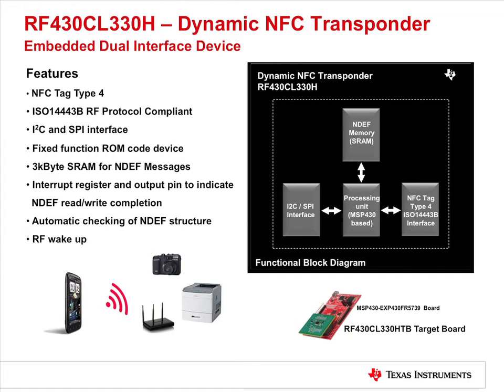This allows NFC connection handover for an alternative carrier like Bluetooth, Bluetooth Low Energy, RF4CE, and Wi-Fi as easy, intuitive pairing process or authentication process with only a tap. No keys or parameters have to be typed in, simply touch the two devices together.